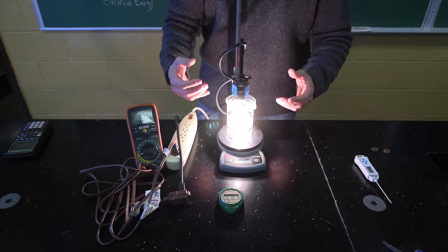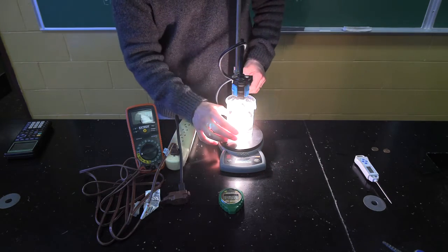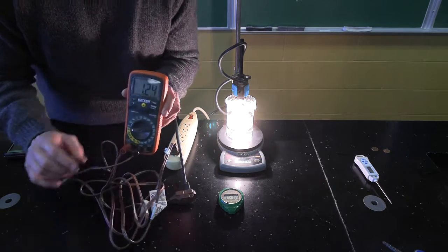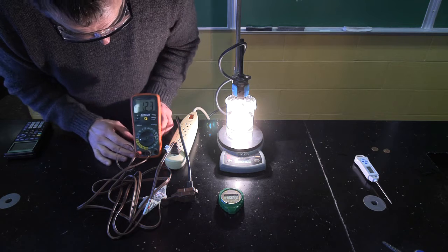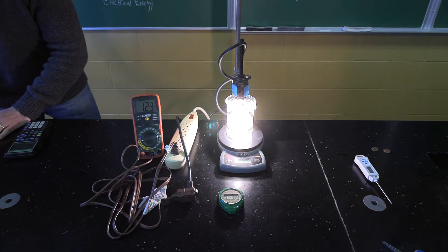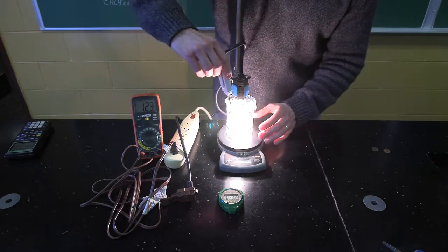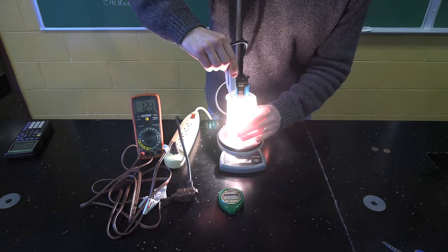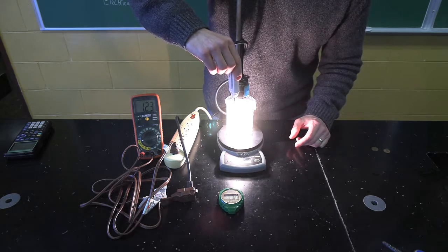I'll be able to calculate them from the measurements of the temperature increase, and that'll ultimately allow me to get the efficiency. Now, I also need the current, as I mentioned, 1.24 amps going to that light bulb. So I will write that down, 1.2, looks like 1.23 amps now, okay. And now I'm just going to wait a couple minutes and agitate this water so that it stays an equal temperature all around the glass of the bulb, so it'll help it not shatter.